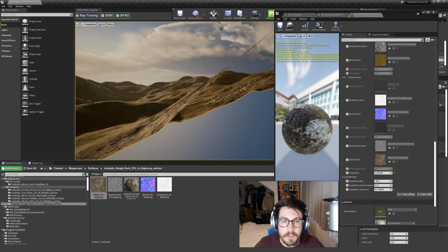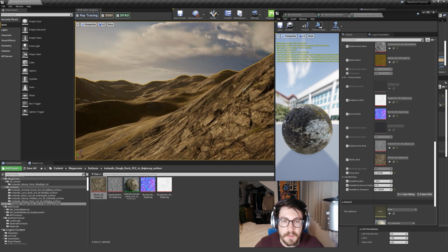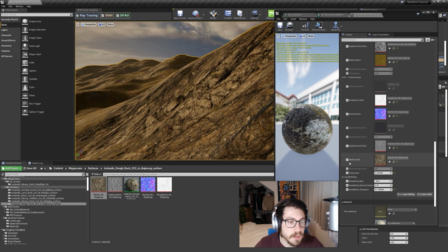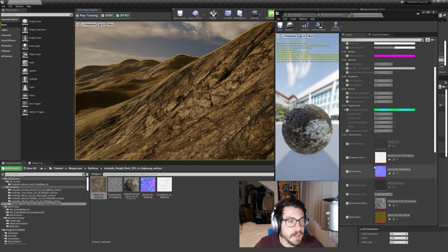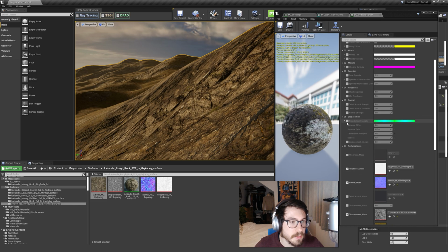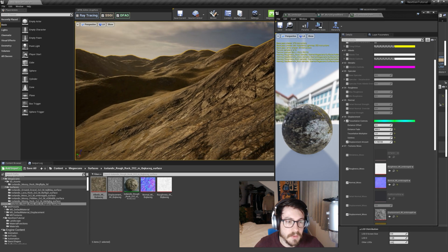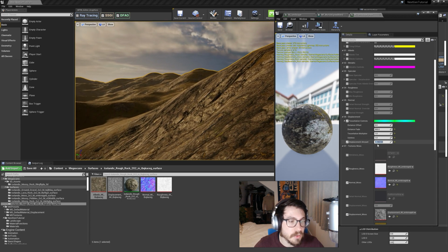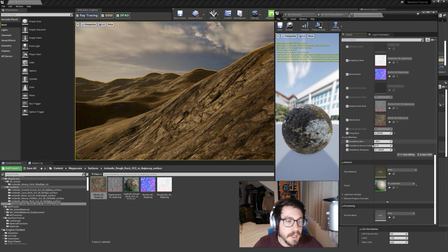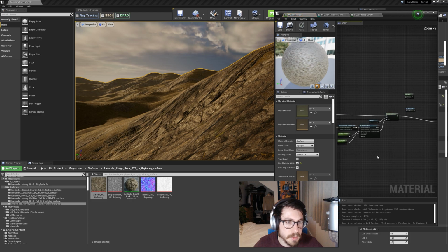And there is no displacement happening right now. As you can see, there is literally no displacement happening. So you need to kind of adjust the displacement settings slightly. If you go all the way up to displacement number 6 here, then we want to maybe increase the displacement amount so that we see what's going on. Sorry, one detail I completely missed is that we need to enable the displacement, of course, in the material.